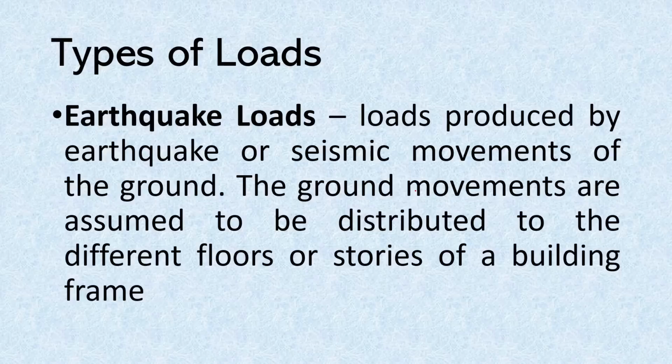And then we also have our earthquake loads, which are loads produced by earthquake or seismic movements of the ground. Now usually earthquake loads are considered as lateral loads. So let's say you have this frame structure, this is your footing, and then these are your columns, and then these are your beams. So earthquake loads will act like this. And we may also consider a base shear force. This is usually tackled in our earthquake engineering.